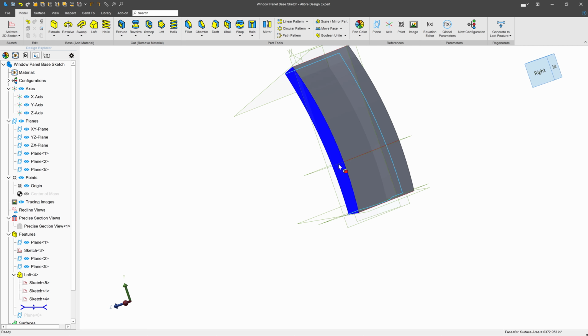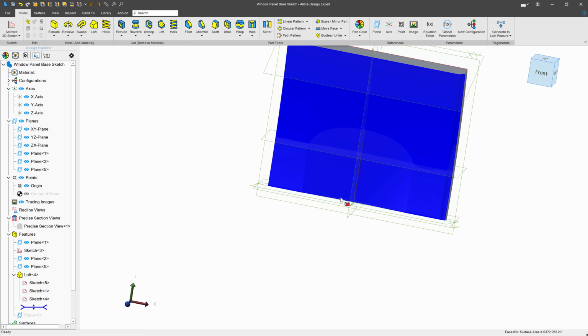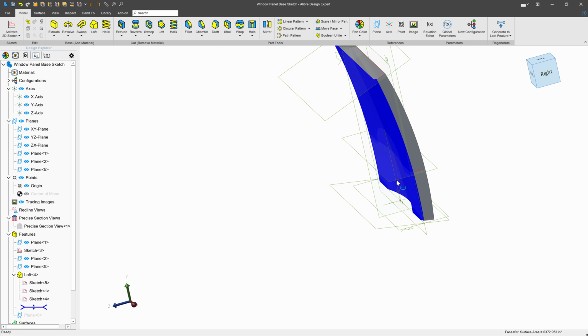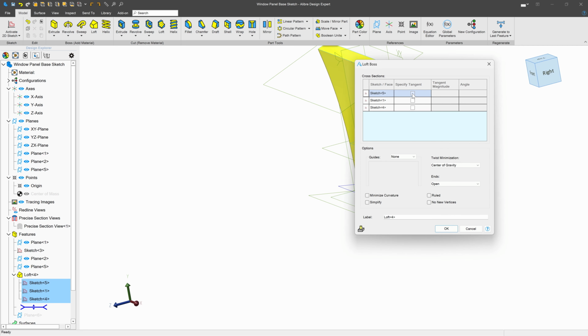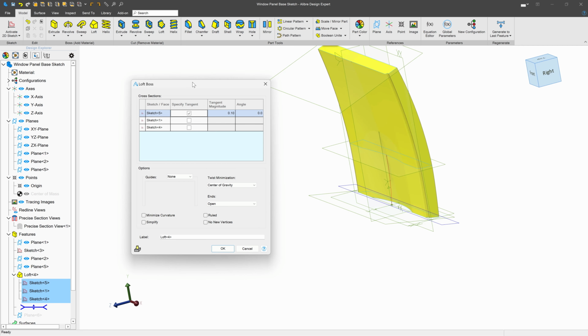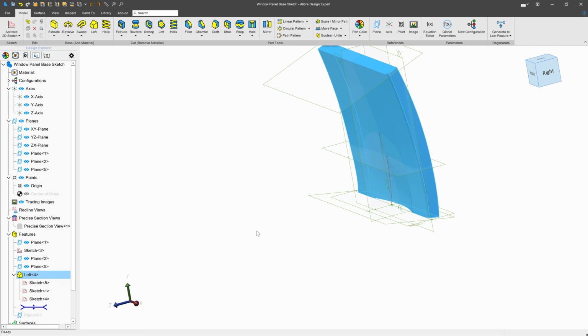And then over here, we just have a bunch of extra thickness. And this gives us a few advantages. But first off, before I go further, I'll set this loft to be tangent. And I'll give this a magnitude of 20. We're working with a pretty large part, so we can afford to be normal to plane pretty well.